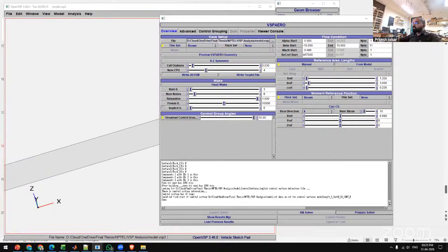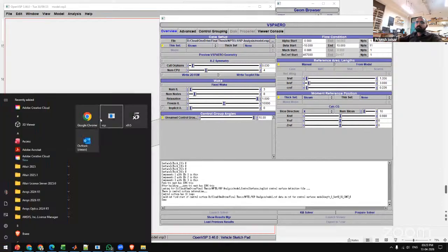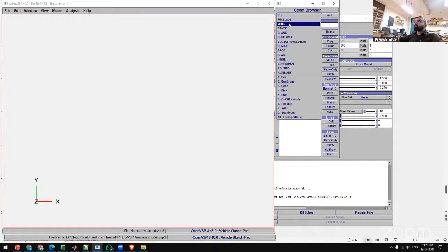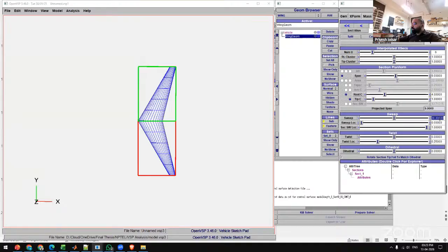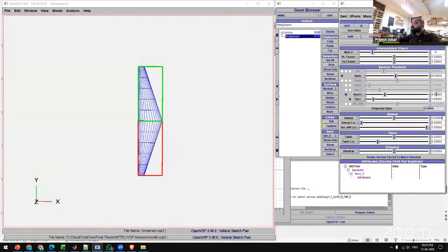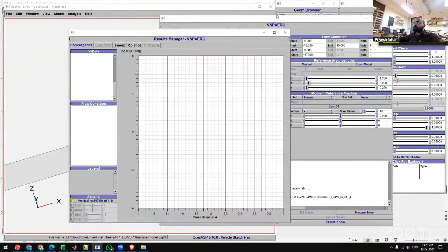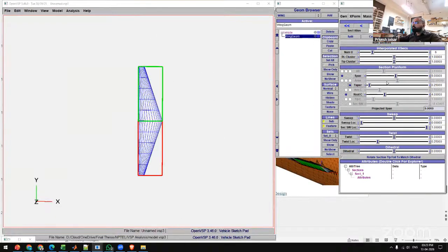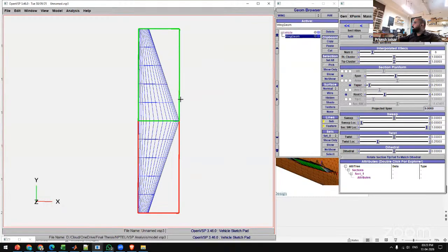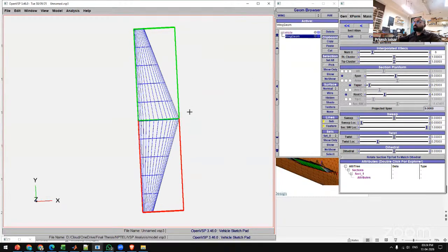Let's take a simple model and see if we are getting the same error. If I take a wing configuration, let's say I want a sweep of 0 degrees, and a taper of... okay, yeah, same issue we are facing here. Let's see a simple problem. Whenever you face a problem, just take a simple problem and see if there is a software problem, because there are bugs in the software. So always take a simple problem when you're facing this kind of issue.